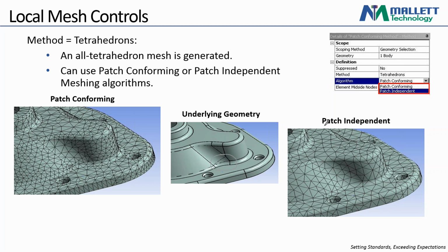So it comes down to a control thing, right? Anytime I see the simulation having more control than me, it gives me pause for concern. Generally, I have the same approach if I'm looking at automatically creating contact bodies. That's almost never going to happen because then I lose control. Then I have to go individually one by one through the contacts to try to determine, was everything applied correctly and was anything missed? It's the same idea with patch independent. If I mesh something with patch independent meshing, I need to go back in and thoroughly examine the body to make sure geometry that I'm interested in wasn't removed. So rather than doing that, I'll just fix the geometry in the first place.